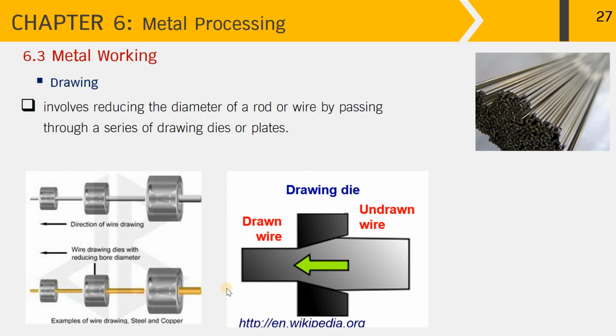The picture in the middle here shows the cross-section of the drawing die set up. Towards the drawing die entrance, it is tapered to allow the metal flow to obtain the drawn wire with reduced cross-section. Unlike extrusion, the operation is made according to the tensile force. So the material properties required for wire drawing are good ductility and a significant work hardening exponent.